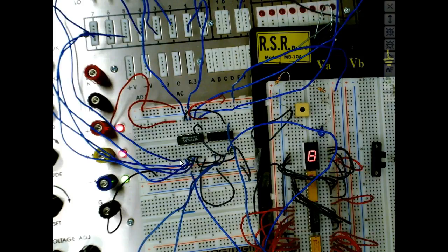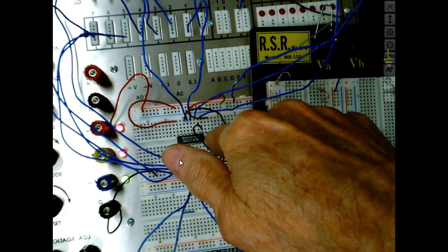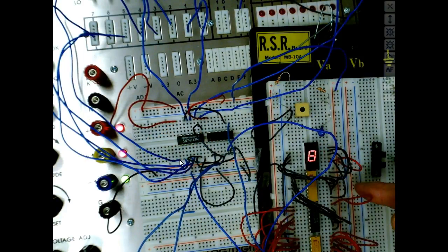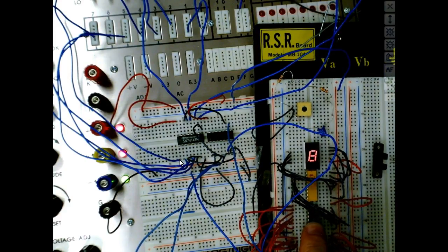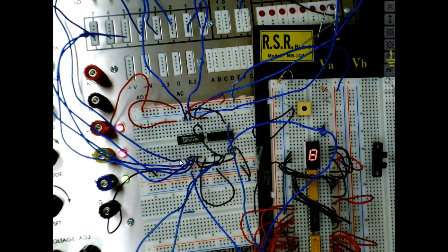And this is a 74147, but we're taking its low active outputs and inverting them to get high active outputs, so we can fit it to our 7447, which needs high active inputs. And 7447 is a decoder, right? It's a binary to what? 7-segment decoder. And there's decoders.